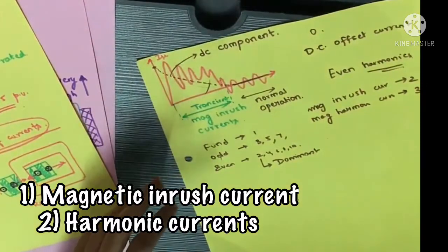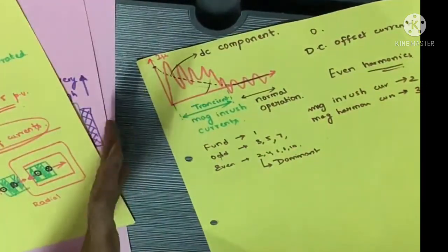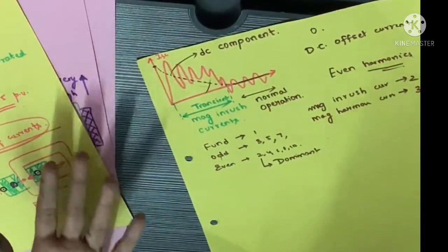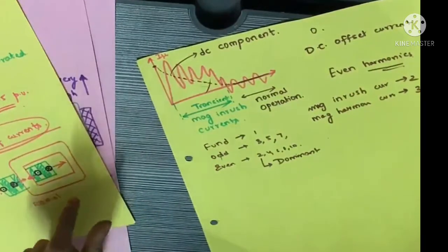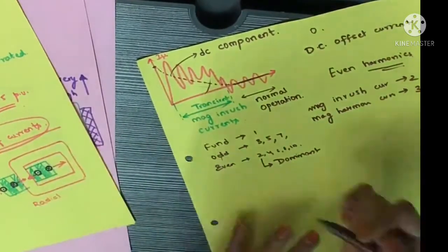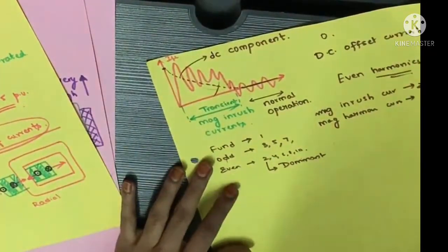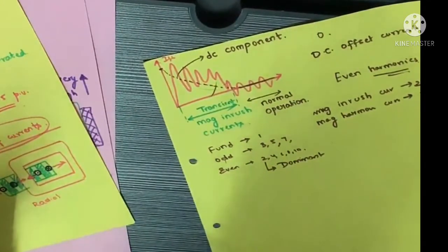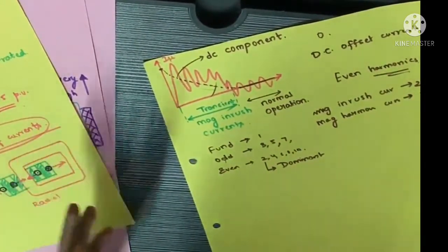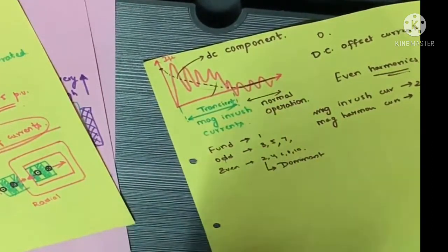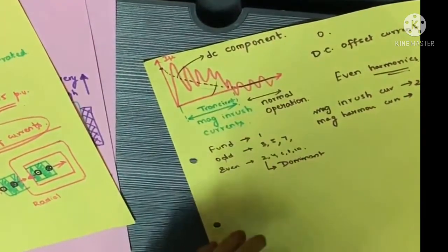So with the modified design of the transformer, that is either the graded or reinforced winding or adding an extra steel channel support to reduce the mechanical imbalances in the transformer winding, the transformer need not be tripped unnecessarily. Generally this high current results in the tripping of the transformer circuit, thinking that it is a fault, but no, this is not a fault, right? The transformer should not be tripped unnecessarily during the switching of the circuit, due to the high magnitude of these inrush currents, which is undesirable.